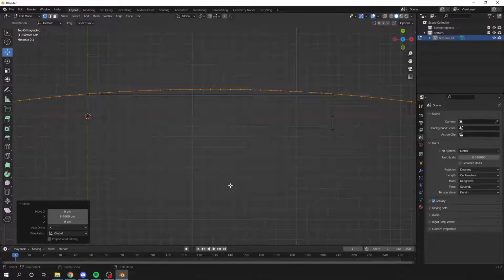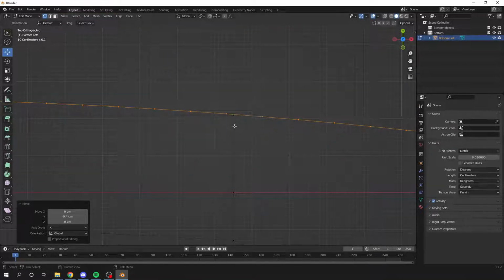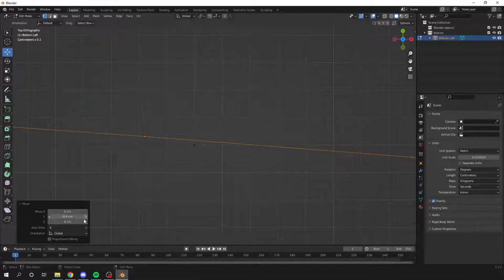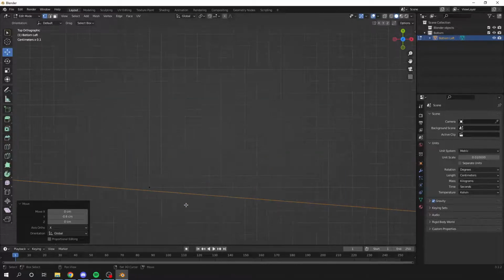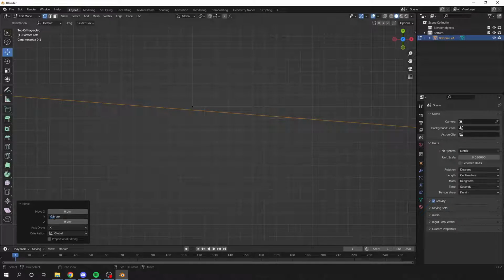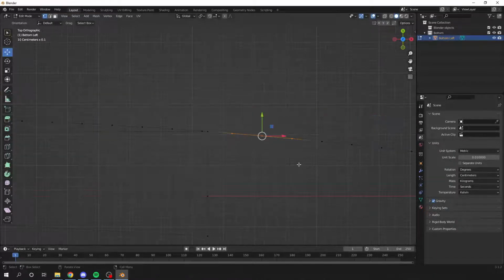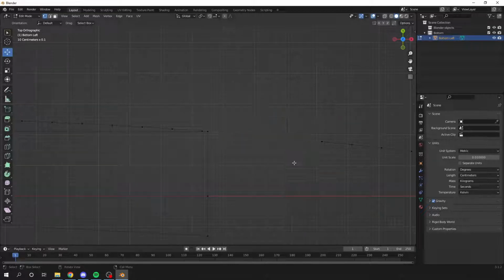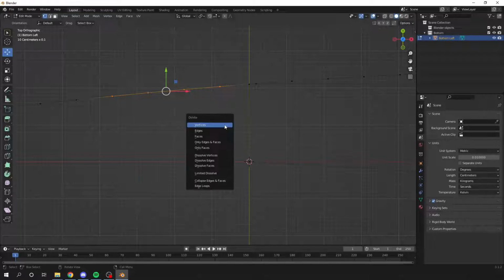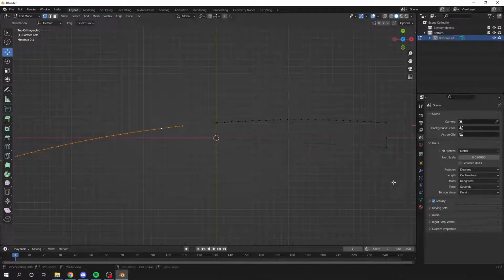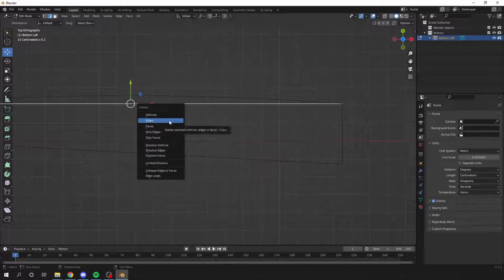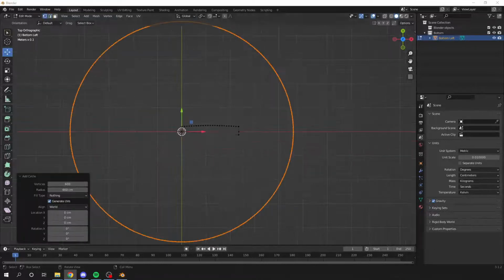I will start by drawing the bottom panel of the boat. The bottom panel has a few changes from the first video. The first one is that the length of the boat is shortened to 2 meters and 35 centimeters. This is because it's impossible to ship the plywood sheets with a longer length than that to a private person here in Sweden. The second change is that the curve connecting to the middle panel will have a height of 5 centimeters instead of 3 centimeters.